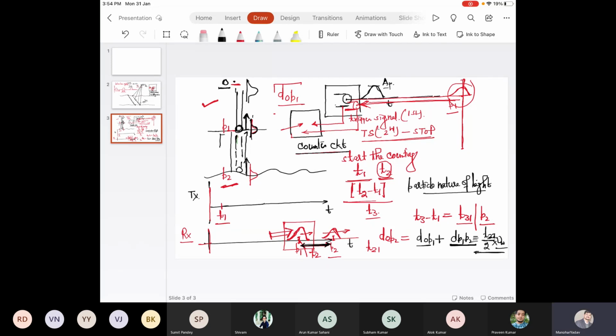So let's see the benefit. When we have 2 interactions, first at the water surface and second at the water bed, we can estimate the depth of water using this bathymetric LiDAR principle. This is an exclusive application of LiDAR. It can penetrate, go into the water, hit the water bed and return back, and we are able to measure the depth of water as well by recording 2 different echoes corresponding to the transmitted laser beam, like this laser beam.